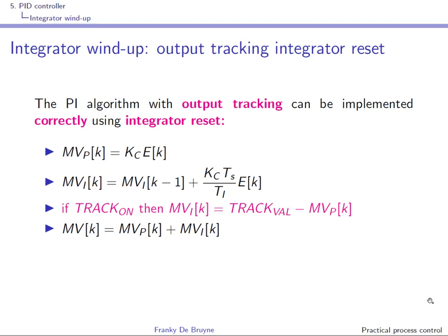In reality, you'll have to combine this with derivative action. So you'll have an equation here that will produce the derivative action, and you will have to add the derivative action, and you'll have to add also the MV feed forward that we have discussed previously.